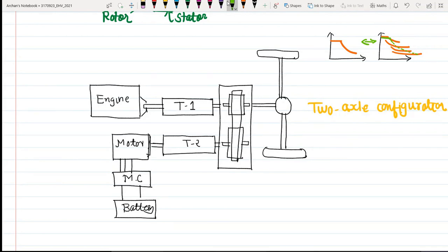Okay, so this multi-speed transmission also tends to improve the efficiency of the engine and reduces the speed range of the vehicle in which an electric machine alone must propel the vehicle. So consequently, it will reduce the battery discharging. Okay, so energy consumption will be reduced.